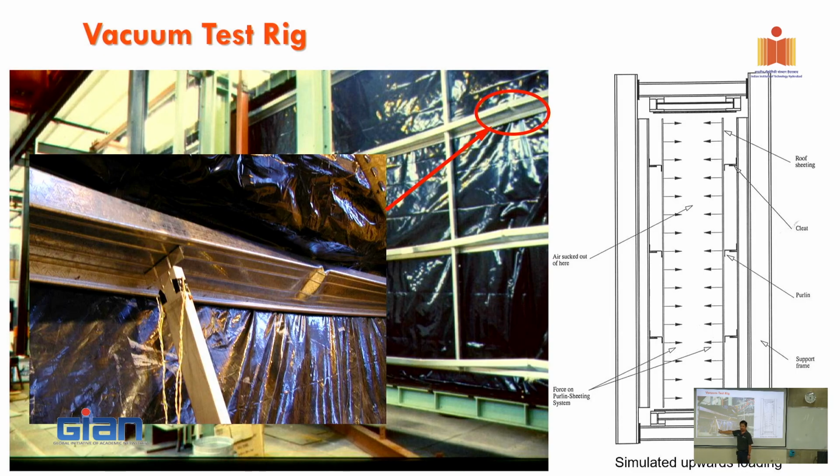That is the rack bridging, the way that we make it in Australia. But here, you use a rod, right? The steel bar, to make a lateral restraint. So it's a similar way to do it, just to provide the lateral restraint in the middle of the span of the purlins. Okay, so this is the failure mode that you look at for local buckling.